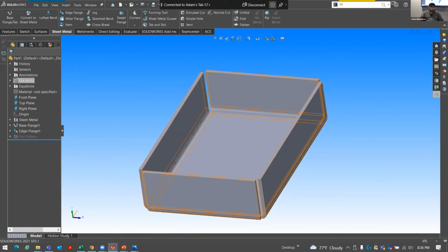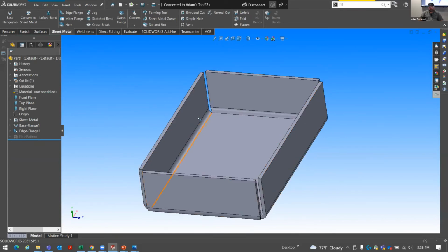Flange length, and that's actually the next thing we're going to talk about. Whether that's in this, or you're adding a flange somewhere else, you can easily expand these flanges and come in and see how they give you the different sketches that are created. I'm going to probably talk about this in my next sheet metal presentation, but I'll talk about it a little bit here. Show of hands, how many people know what a minus sign next to a sketch means?